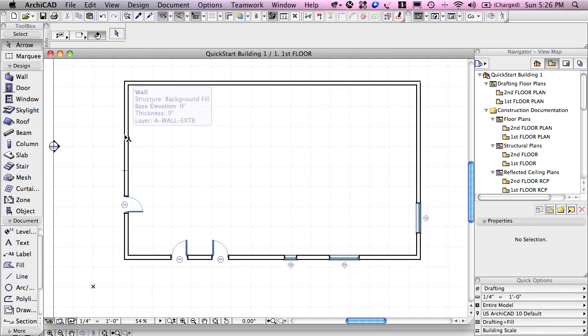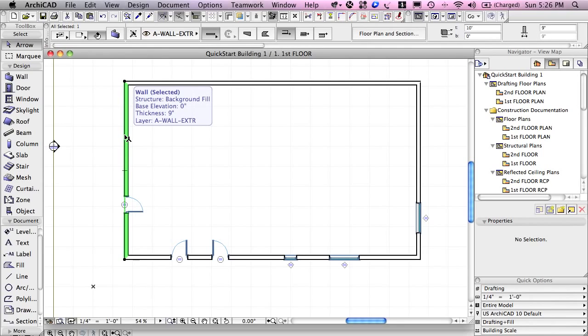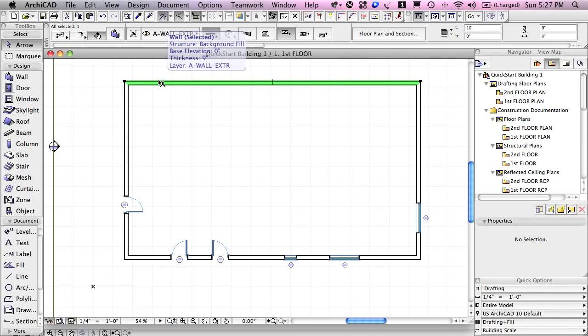I'll go back and again click on this wall, and this time I'll go up to this other wall on top and position my mouse there, and you can see that again it has the pre-selection color blue. It shows that there's a wall, the little floating information that's translucent, and when I want to select it, I click, and you see now it's changed. So by clicking, I've selected this one, but I've had ArchiCAD just ignore or forget the other one.